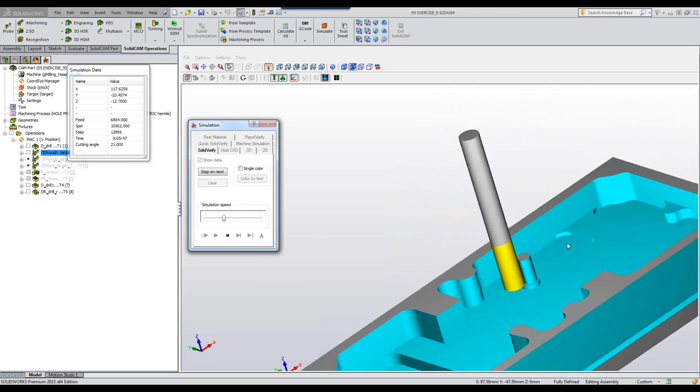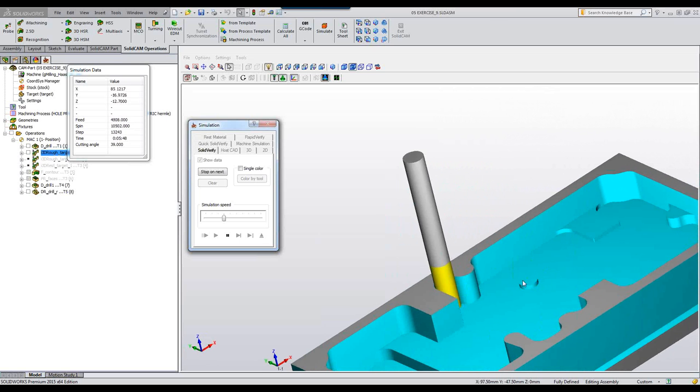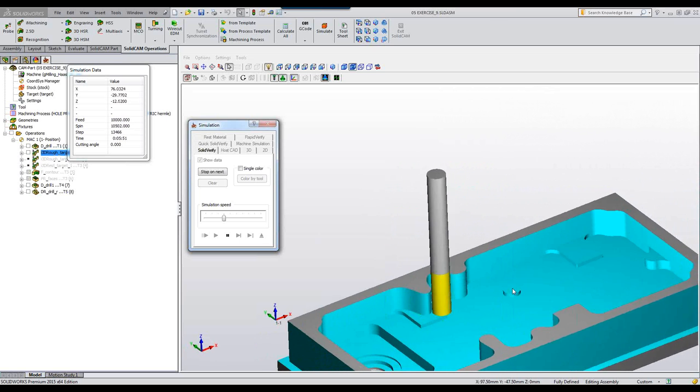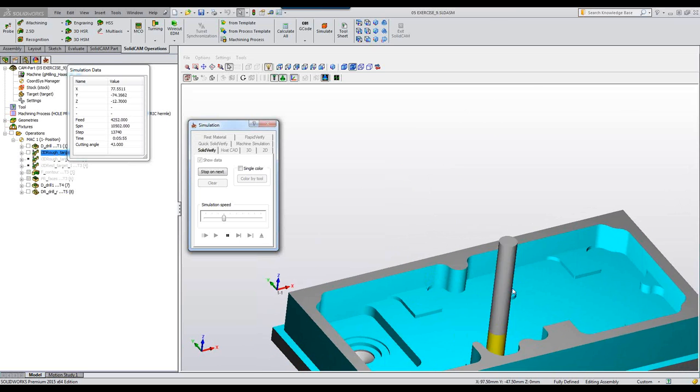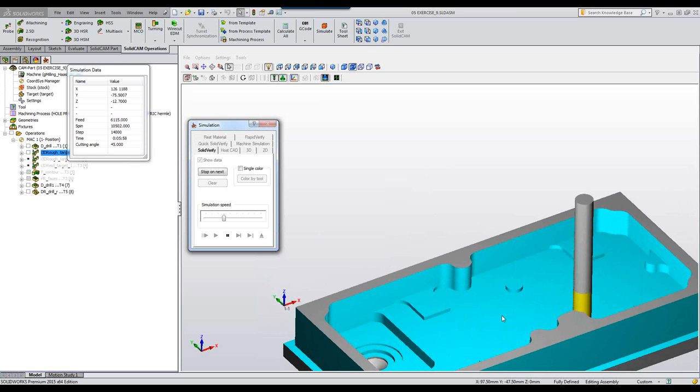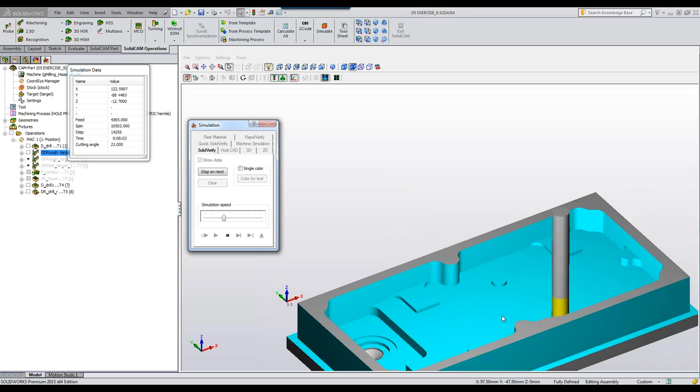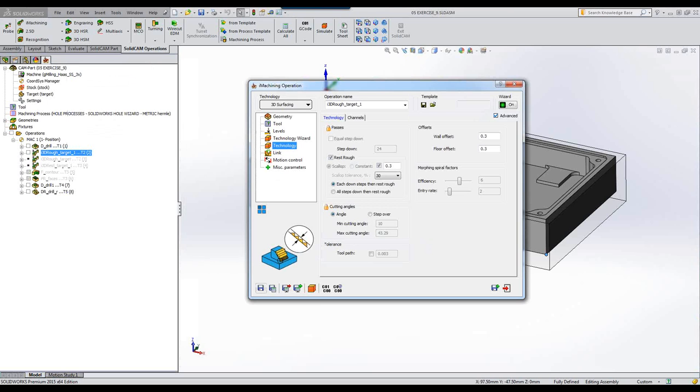It first localizes and works only in that area, so it minimizes the repositioning of the tool itself, working on each individual step. Now when it finishes this, it just goes up to the top and finishes off the top of this part itself. Okay? This is what we have with the step up, the optimized step up that I was talking about. Now, if I would go back to my other screen for a moment,